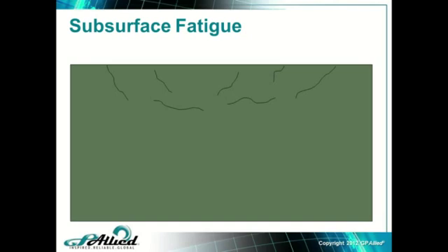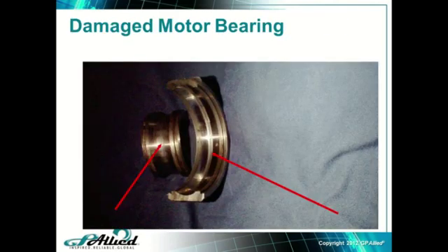So as that roller passes by and puts a lot of strain inside those cracks, and those cracks start to move, sides of the crack move relative to one another and they're scraping against each other. That's that super high frequency stuff that the ultrasonic stuff picks up very, very well. If you have a modern vibration analyzer, something that's capable of envelope demodulation, you can turn that on and you can hear this as well. Well, you can't hear it, but you can see a spectrum and waveform of it, right? So the cracks connect, looks like this.